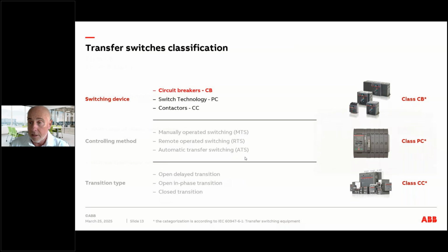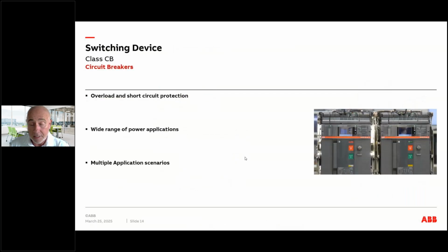So we'll take a look at the circuit breakers. As you can see there now, there's a picture of 2 air circuit breakers. This is more in line with upstream power control, say 2 incomers to an LV switchboard where you want to do some switching from mains to generator, etc., or mains to mains. Again, we'll touch upon some of the more common ones a bit later on. But again, you can use power circuit breakers, ACBs, and molded case circuit breakers.